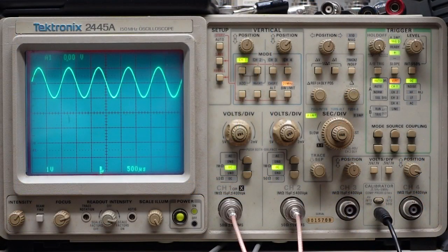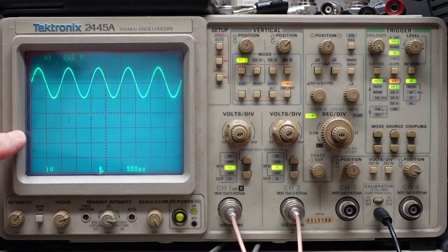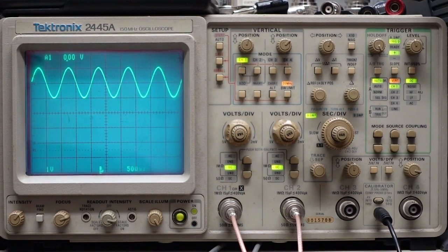Okay, the first thing I want to do is to show you how to set your oscilloscope up for 2-channel operation. This is something I very commonly do because I work on stereos, and I always put the left channel on the top trace and I put the right channel on the bottom. And I do the same thing the same way every time. If I'm using multimeters, I have 2 stacked, one on top of the other. The top one is always the left channel, the bottom one is always the right. I always tell people I'm training at work, do the same thing the same way every single time.